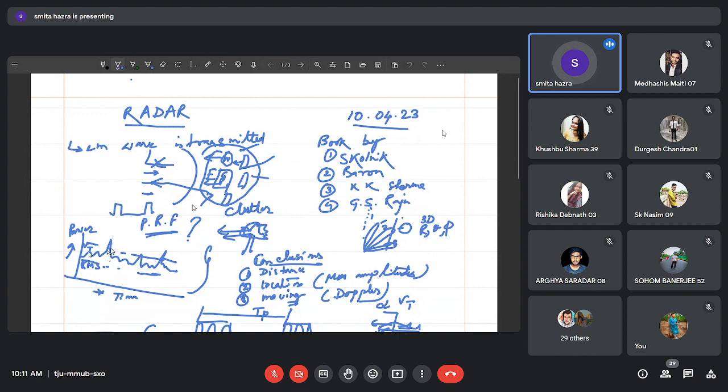The source of that extra energy is the clutter or the background, some extra component of scattering cross section, and because of that, this extra excursion is there. So that is the normal expectation or the normal phenomenon. Okay, so if we make VT lower to catch the weaker echo or the weaker target signals, then what happens? Often it misleads us by exceeding the level of the VT. So this is a kind of problem which is known as the false alarm probability.